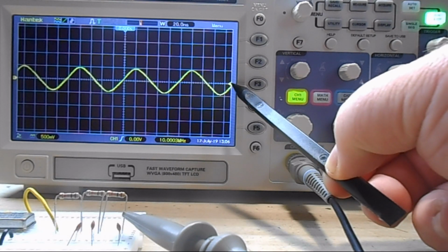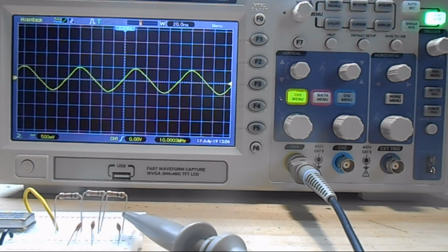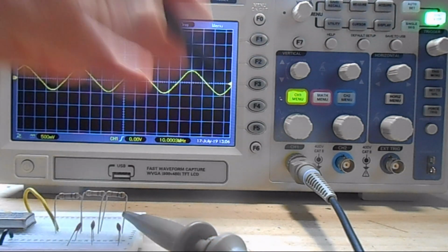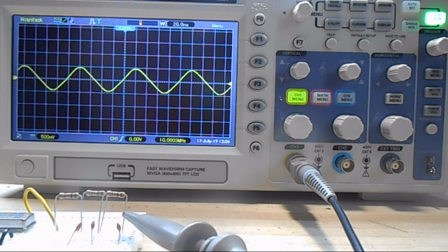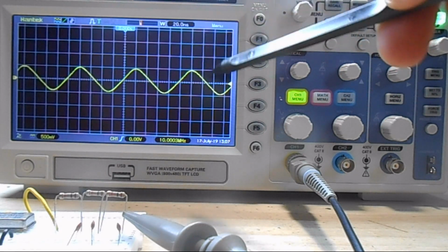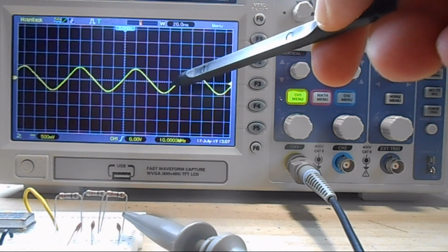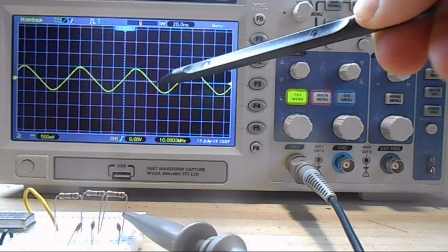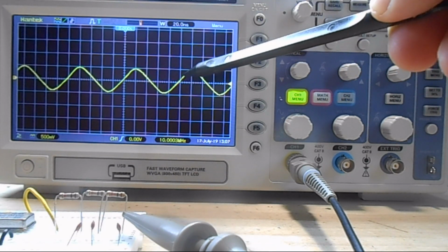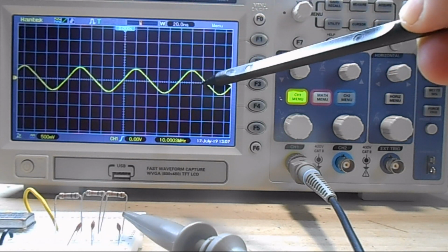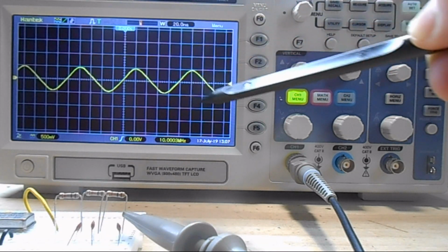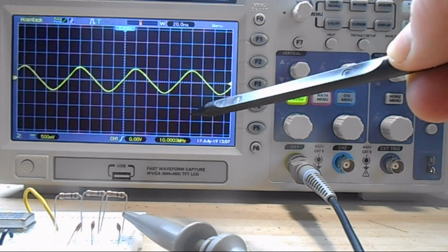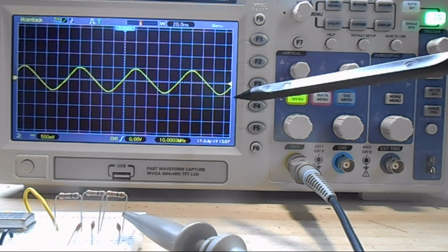The trigger system, which is marked by this point here, is where it's going to start reassembling those sampled points of the signal we talked about and showing them to you on the screen. Remember, most signals captured by an oscilloscope are continuous, without end. So if we take a 1 megahertz clock signal, an edge happens every 500 nanoseconds, okay? If the scope were to show this on the screen, it's way beyond our ability to actually see that signal. So instead the scope is going to show us a rolling sample of the signal.